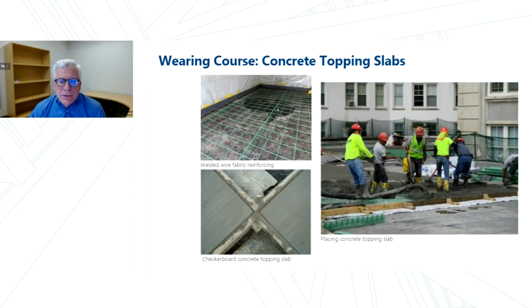Here's installation of a drainage mat. On this one, the contractor is placing it on welded wire fabric on top and then putting the joints in as they go. So really, it's very consistent with normal concrete practice.